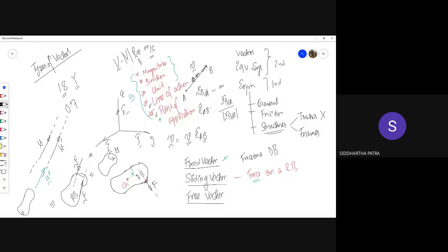Here we are actually doing a little bit of equivalent force system as well, which is in our syllabus, the second chapter. I mean, the same couple could be created by the same two forces, but this time oriented in a very different direction, maintaining the same distance. Or the forces could be multiplied by 2 and the distance could be divided by 2 and the direction of the forces could be changed. And even it can be shown that the same moment can be created by applying,